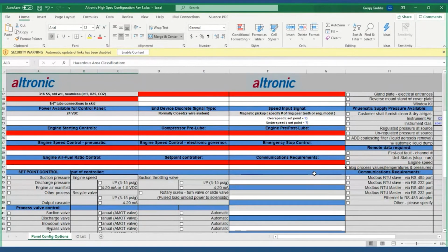Say, for instance, you're doing a refurb with a unit that's out in the field that's talking to a PLC or SCADA system out there. A question to ask them is, hey, is there a certain pattern you want that Modbus to read? In fact, you might even point out, here's our standard Modbus map. Is this going to work for you?